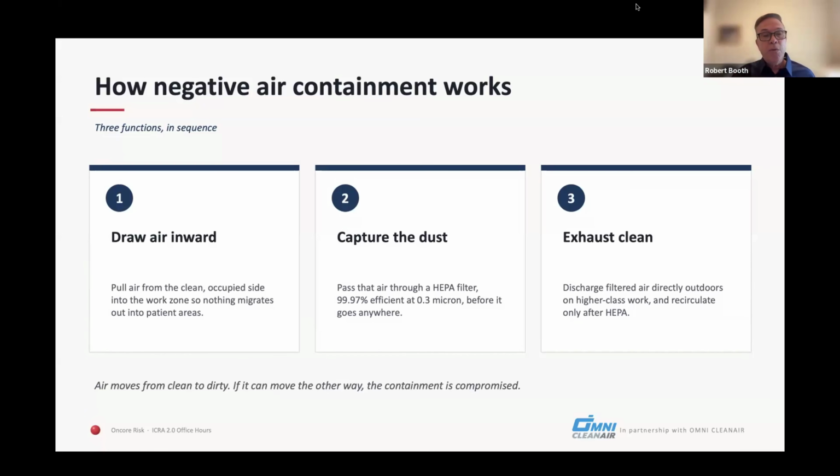If it's going to go through a HEPA filter or if it's going to be exhausted outside, one thing we want you to remember is it has to go through a HEPA filter if it's within 25 feet of an outside air intake. The other item there that we see challenges with, and I know Josh will talk more about this and Emily will too, is that when you're exhausting into another space, you have to make sure that it is HEPA filtered, but you also have to verify that on a routine basis. And then some of those pressure issues can be of concern.